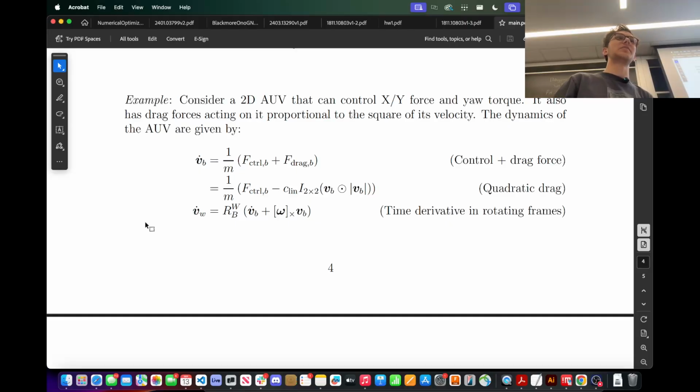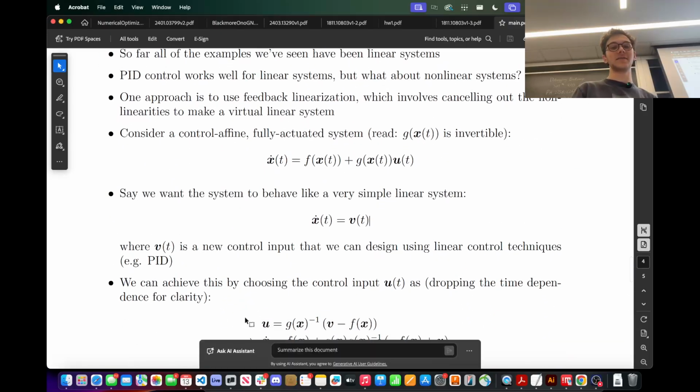The way that we do it, because we don't have CFD, we don't have people that are very good at doing CFD, and our CAD model was bad for a long time and didn't have the correct mass properties, is that Theo, who was doing the state estimation thing last time, wrote an online parameter estimator. The core idea is we have sensors on the vehicle that can measure real quantities like acceleration, angular velocity, and linear velocity, and we have this model of the vehicle.